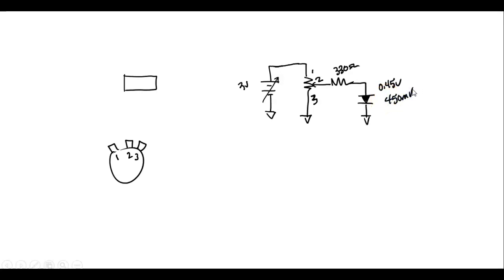And then what we're going to do is measure the current. Well, we're not going to measure the current, because normally, what do we mean by measure the current? That means I'd have to break the circuit. I'd have to put my ammeter in there and measure it. I don't have to do that, guys. I got a 330 ohm resistor. And I know I equals what? Okay, so that means I can calculate my current.